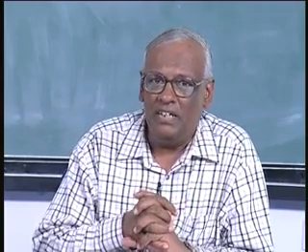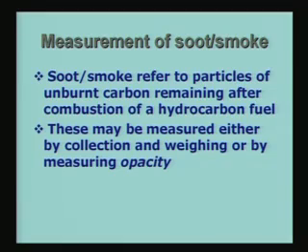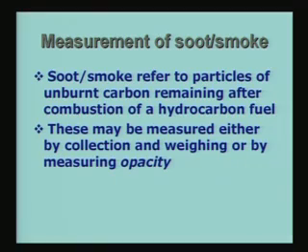The other method is to measure what is called opacity, and this can be measured in situ, that is, you do not have to collect a sample, the in situ measurement is possible. For example, in the case of a smoke stack, the instrument, the opacity meter, can itself be mounted on the stack itself, so that the measurement can be done directly in situ.